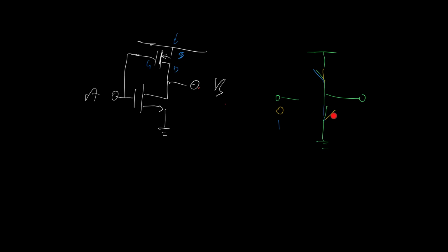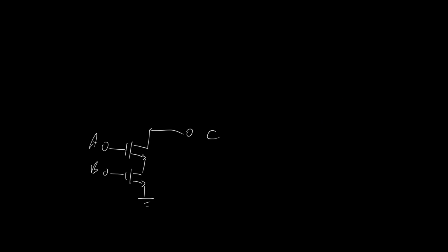This is true for our NAND and NOR gates as well. We saw in the last lecture how by putting FETs in parallel or series we can implement NAND and NOR gates. We replace the pull-up resistor up here with some p-channel FETs, and we arrange them in such a way that whenever the combined bottom switch is closed, the combined top switch is open, and vice versa. And that's precisely how logic gates are made using FETs.